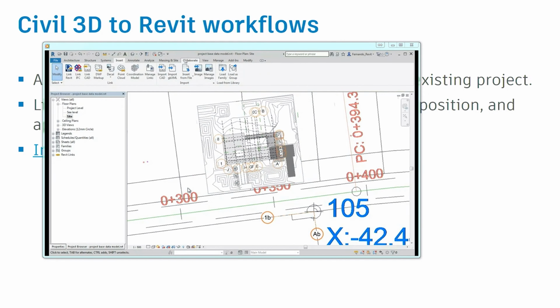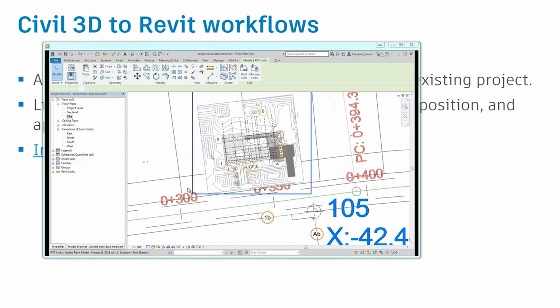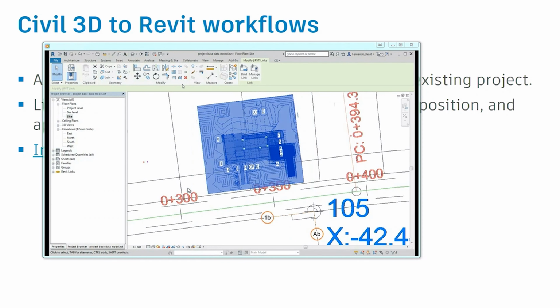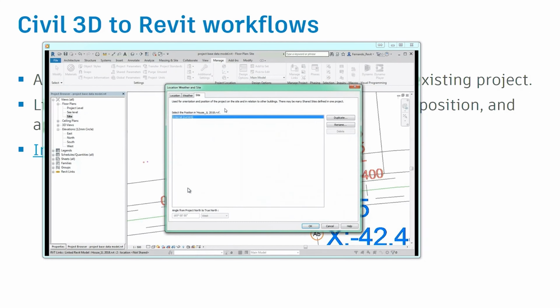boxes so we can control the visibility of our objects. Very mandatory in these big projects. Use a lot of scope boxes, associate views to the scope boxes, and manage the visibility of the scope boxes. I don't want to drive around the model looking for my objects. So we create views, we name the views for the different entities, and that way we can manage our model.